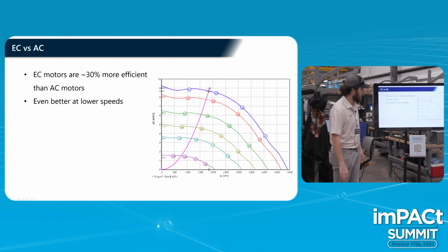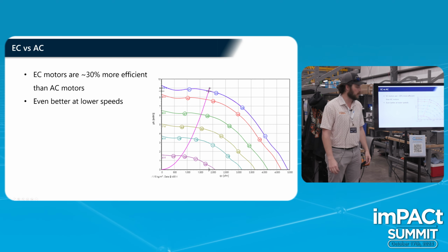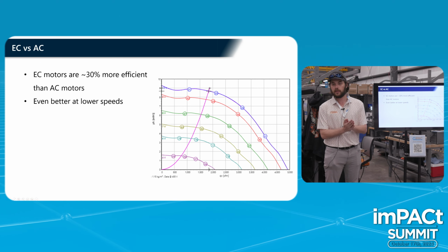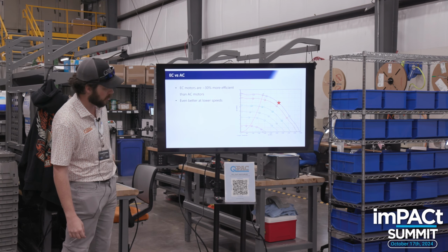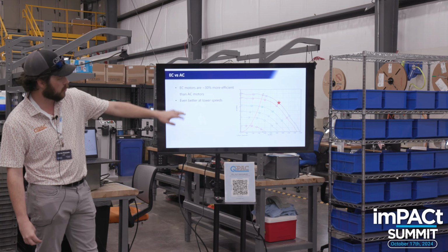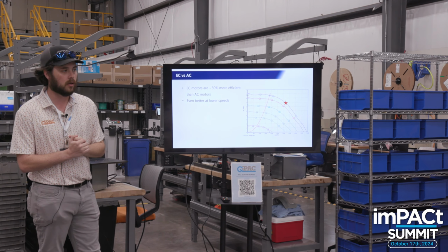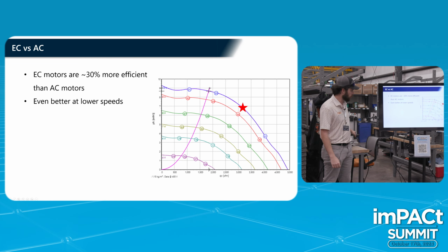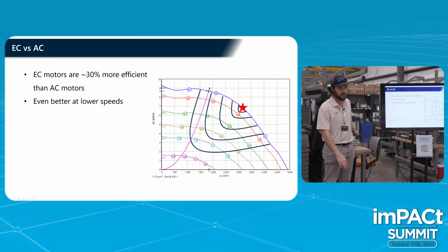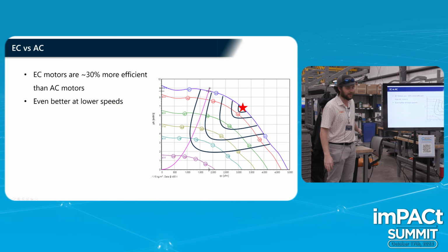All right, here is a performance curve of one of our plug fans. Can anybody tell me where on this curve would be the maximum efficiency point? So we're looking right about there, a little bit lower. So that's going to be about your maximum efficiency point, and it'll follow a trend somewhat like this. Not exact. I drew this in paint, so don't look too closely.